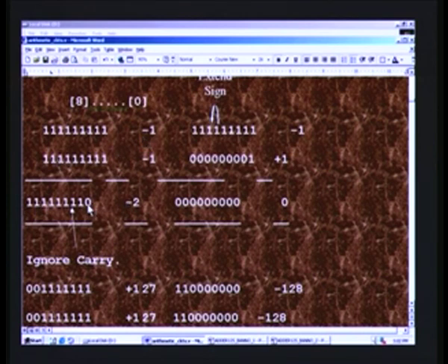And if you take the 2's complement of this, you will get this as 1. Okay, this need not be done, we are just merely adding here. This MSB is the sign bit, so minus is there, and the first one we encountered is this here, and we retain these 2 bits and make the other bits 0. That is the shortcut notation we have already seen. So this is nothing other than all zeros 1 0, which implies 2.